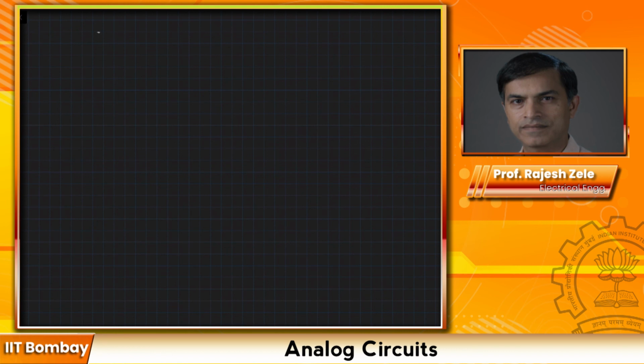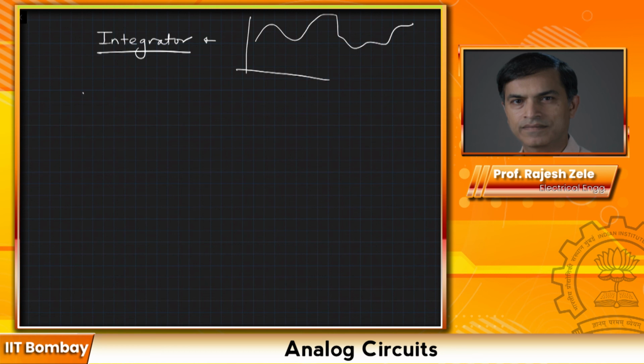Next, I'm going to talk about the integrator circuit using an operational amplifier. What does integrator mean? Let's say here is a waveform that's going like this. Then integrator means you look at the area under the curve. You will take each value and sum them all up. So an integrator is actually trying to figure out the area under the curve.